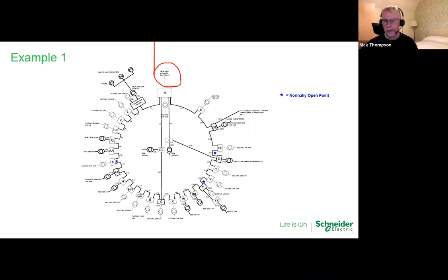Now we're totally reliant on additional information on this single line diagram. I'm not showing it here. We're showing where the open points are. That could be a link box for all I know, or it could be a ring main unit that is possibly 40 or 50 years old. We don't know. We don't know whether they're going to move these open points around on a regular basis. Some sites will have that as a matter of course, moving the open point down regularly to exercise the switches. The DNOs will move those around operationally as required.